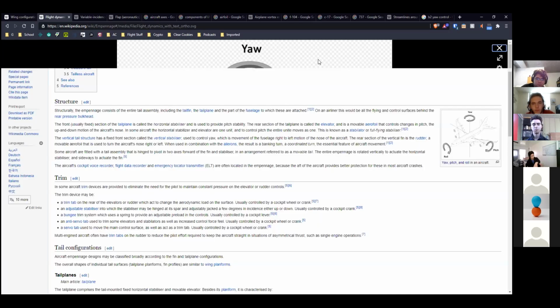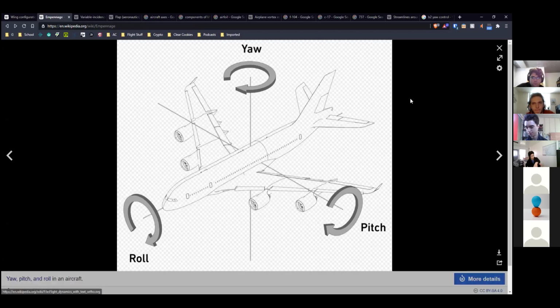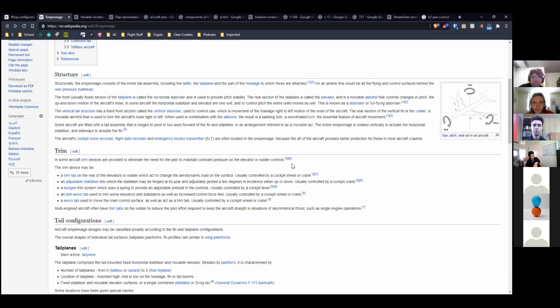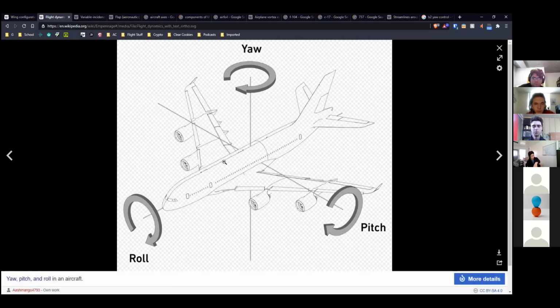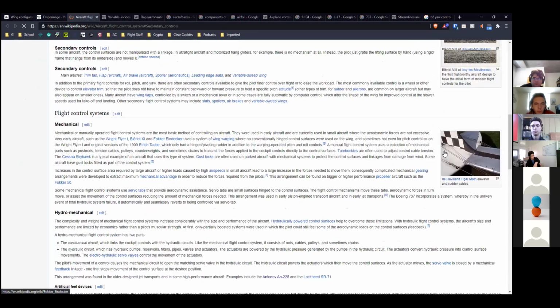So to make it so that the pilots don't constantly have to be holding in control inputs all the time, which gets very tiring, trust me. They have like a PID system? In computers, yes, but the original system was literally just a wheel or a thing you could move, and it would move a trim tab, which I don't know if there's a trim tab shown on here, but there's probably one shown on here.